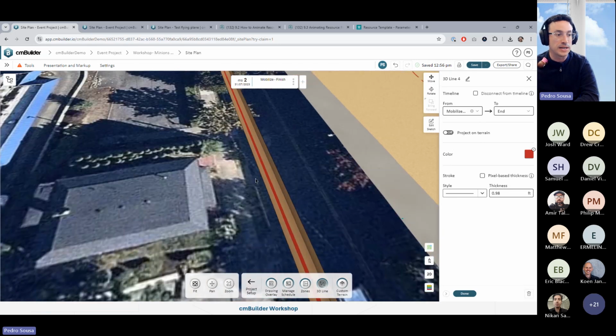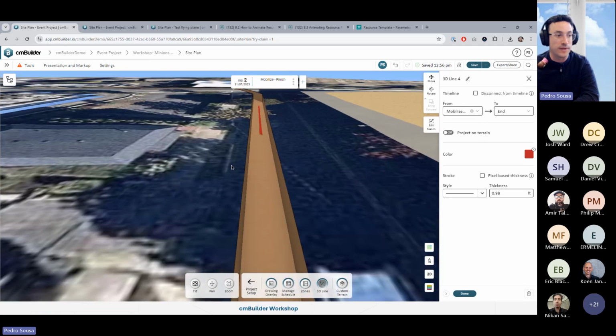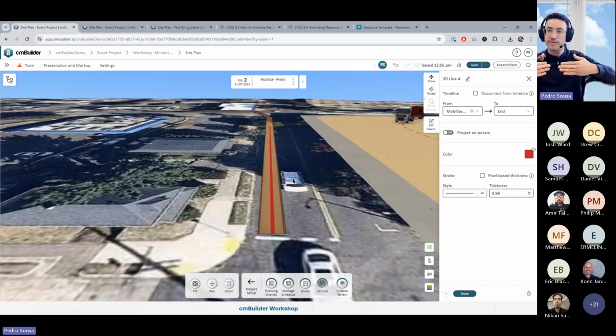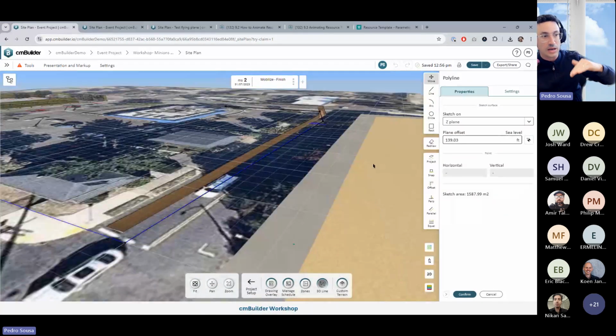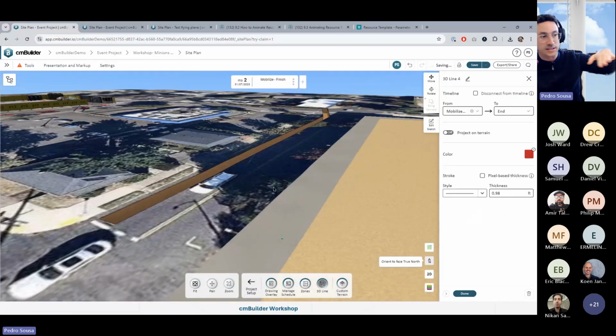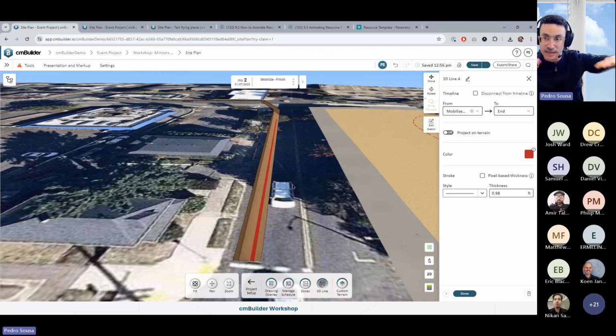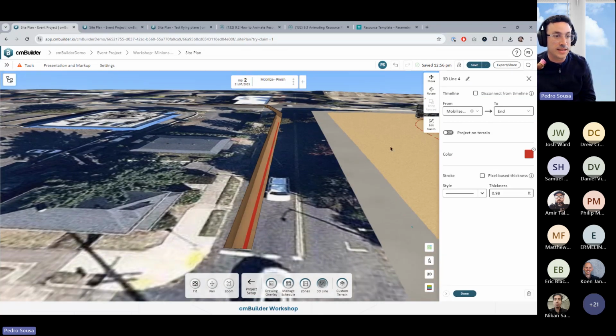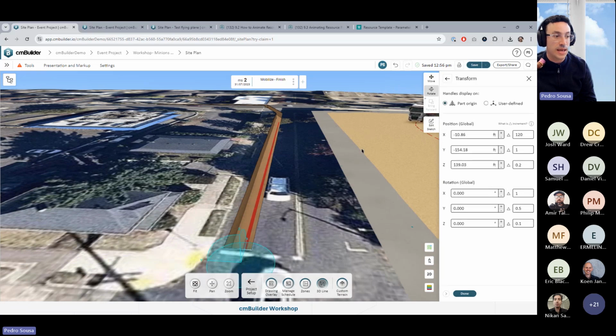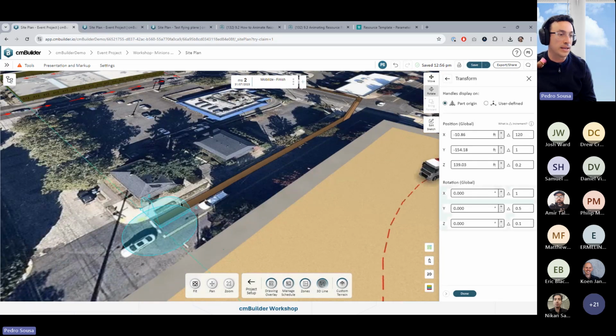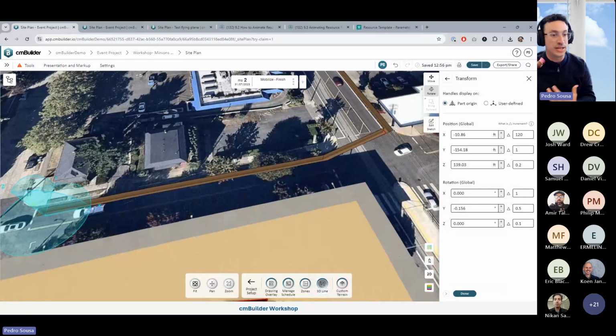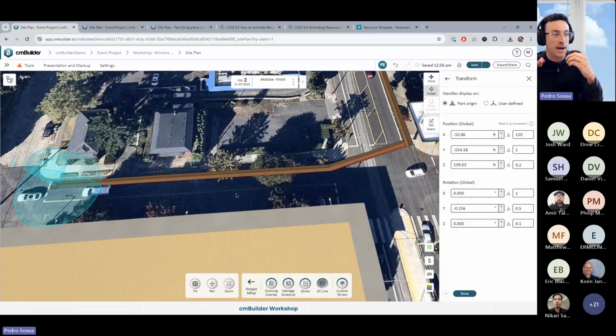The reason is that this line was created with a flat surface on the sketch, right? By default, the line that you create will always be flat along the z plane, right? To adjust that, you can go over here to the rotate function, and then you can either click and drag these dials to adjust it, or, which is something that I usually suggest, you can use these controls over here to do minor adjustments.